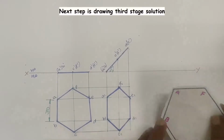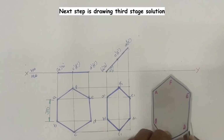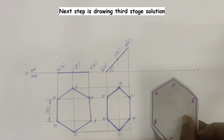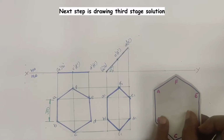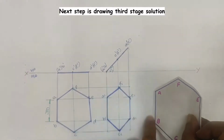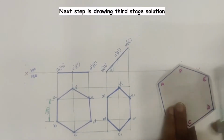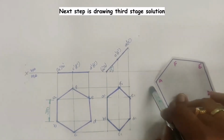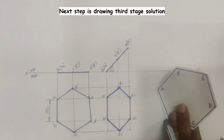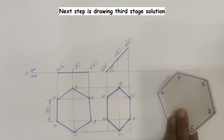In the second stage solution, the hexagonal plane is resting on its side on HP and its surface is making an angle 45 degrees to the HP. Whereas in the case of third stage, what we need to do? The side which is on HP, say AB, which is perpendicular to the XY line in the second stage, is to be tilted with an angle of 30 degrees to the XY line. In this position, we need to draw top view as well as front view of the plane.